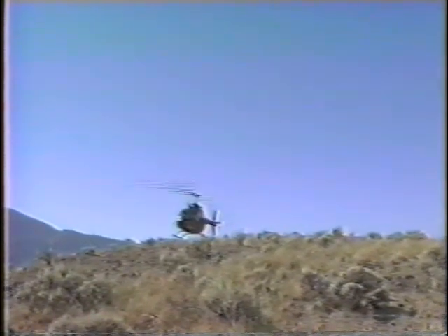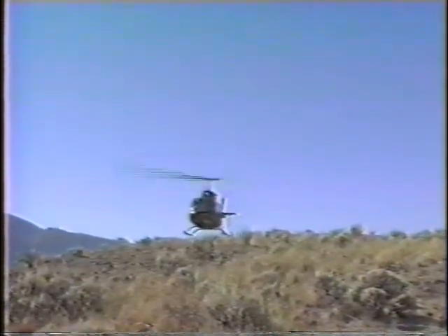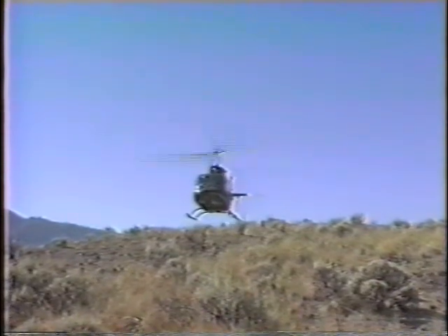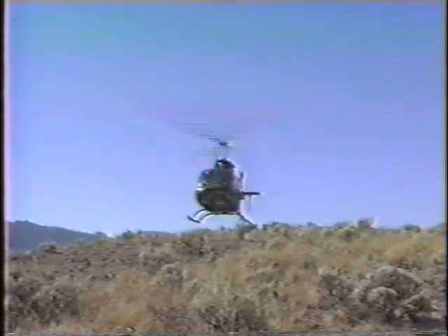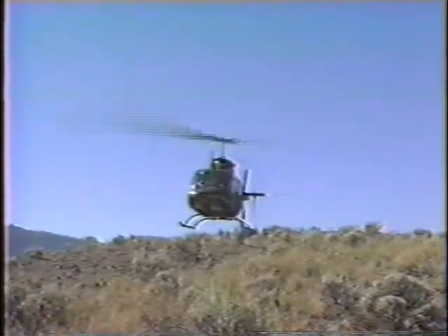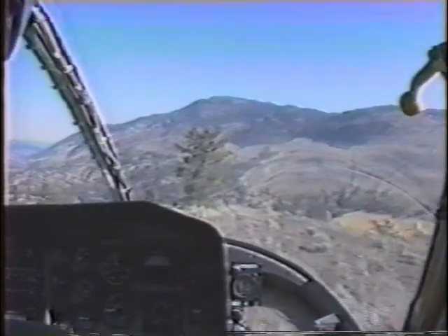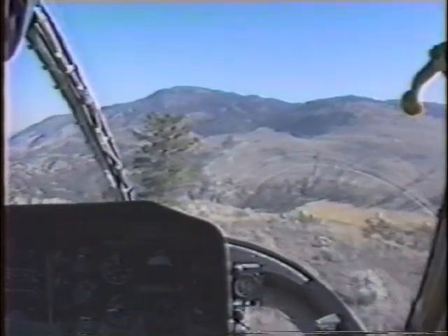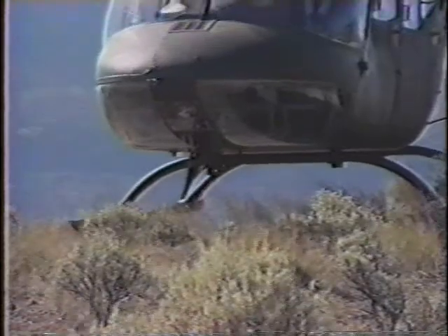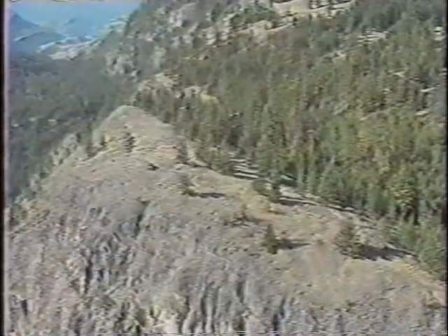Other key things to watch for are wind from the left can cause unanticipated right yaw. A light should go off in your head whenever winds are quartering from the left. Try to keep crosswinds on your right to save power. Make sure the aircraft is flown in trim. Crabbing is necessary. You'll use less power that way too. And above all, never land on a bad approach.